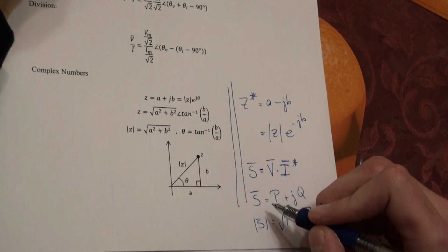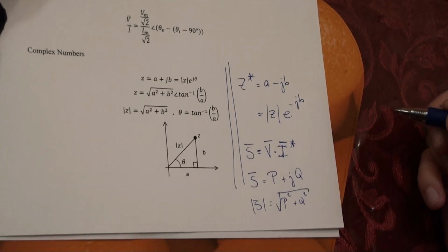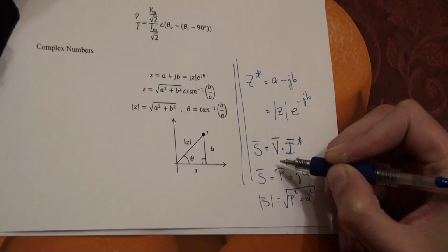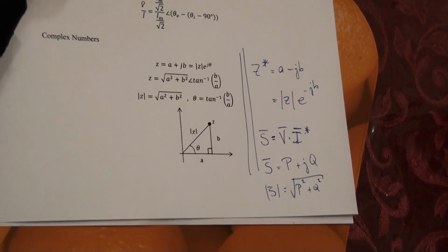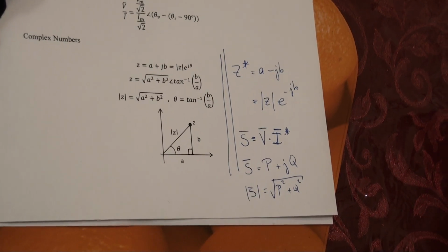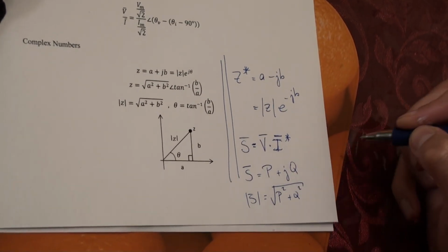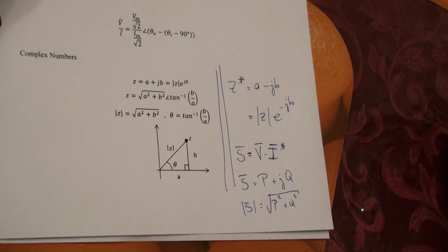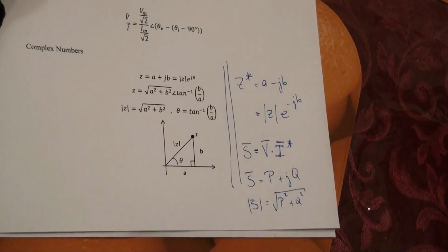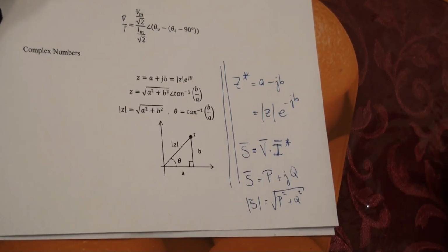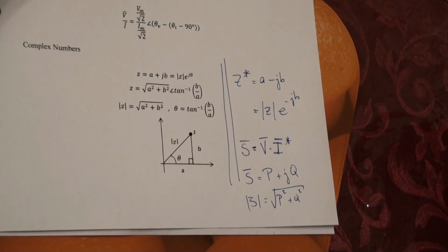Now, complex power is additive, but apparent power is not. The reason complex power is additive is that here you have it in rectangular form, and here it's an absolute value, which doesn't add. So make sure that if you're adding, you're adding complex powers, not apparent powers. Don't make that mistake either.